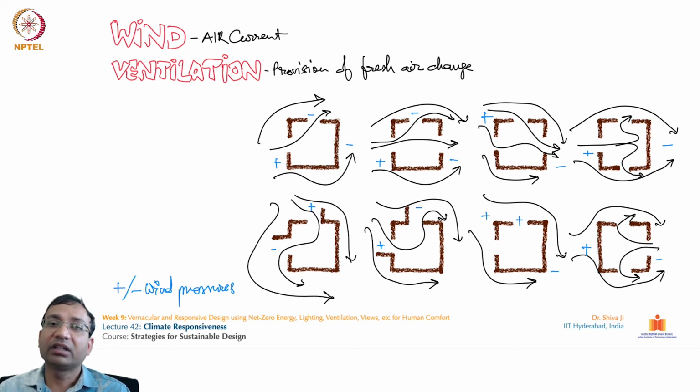Further to this, what could be the other strategies? Ventilation is one of the very important requirements of any building. How can we plan the openings in our building, because there is always some wind, even if it is not very fast? How can we create high-pressure and low-pressure micro zones to induce the wind inside our premises? This slide talks about that: how we can promote cross ventilation and a staggered way of wind movement, and in case it is not needed, how we can avoid it.